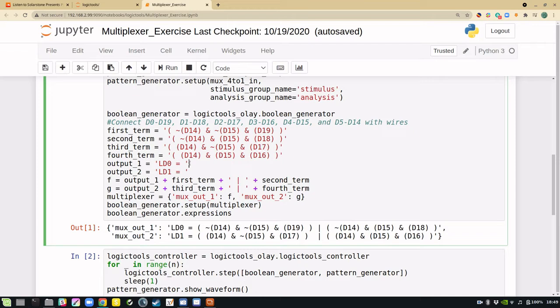for example, an LED. However, we can't do that due to a technicality on the board, which is that all logic functions are created in a certain way in a lookup table. A lookup table is a way of generating all possible logic expressions given a certain number of inputs and outputs. And it turns out the maximum number of inputs for any one output is 5. We can have 1 to 5 individual pieces of data that flow into an output in the Boolean generator.